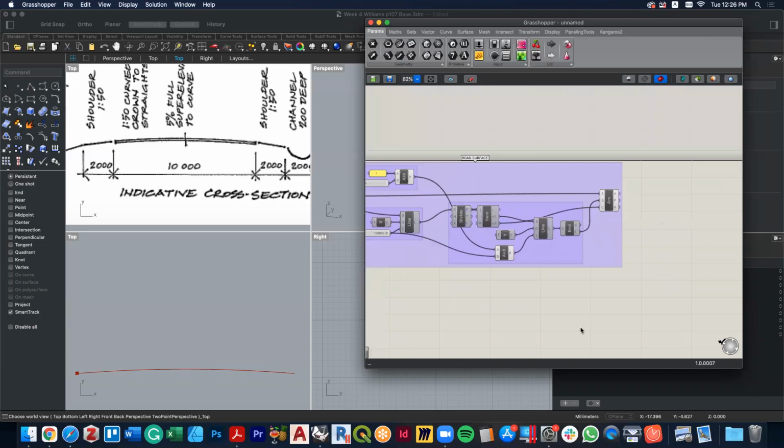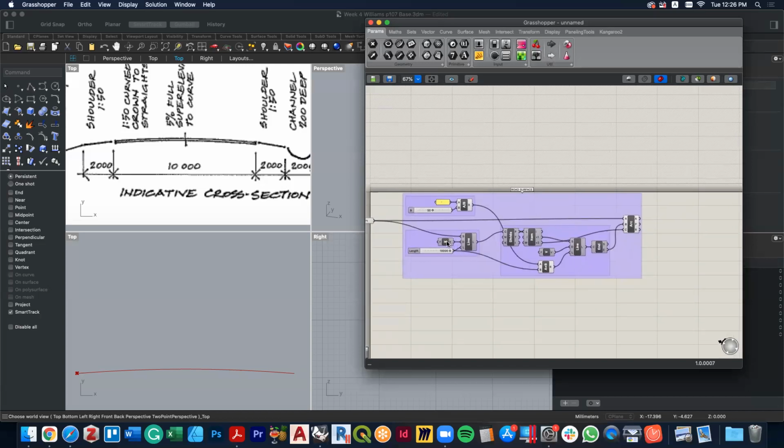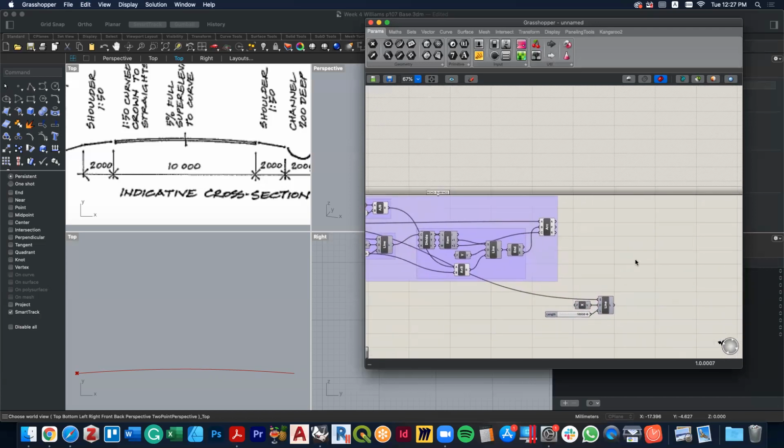Now, interestingly, we can do this in a similar sort of way, where we can copy, which is what I'm going to do. If I get all of those three components there, and I hold the Shift button down and press Control C, Control V, I then have all of that pre-made line.